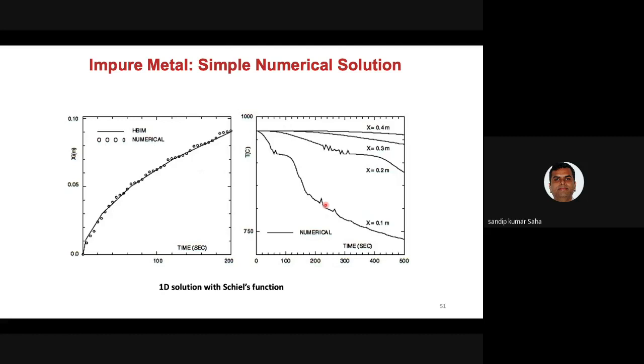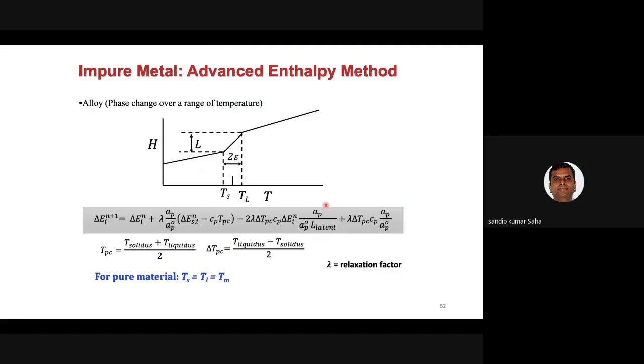Okay, the species equation actually calculates the percentage of that component or composition during the phase change. So if you don't have that species equation, that means you have to rely on the latent heat versus T solidus and T liquidus, the liquidus temperature and solidus temperature. Okay, so modeling will be in that way. Okay, so that modeling is very simple, like for pure material only.